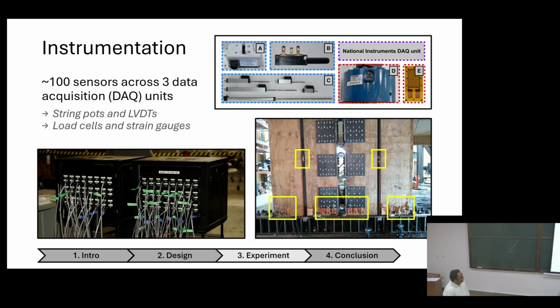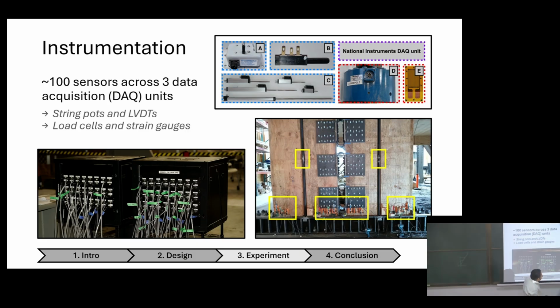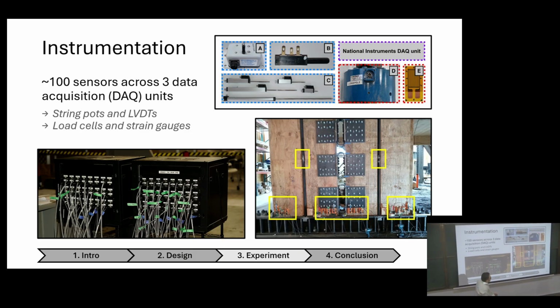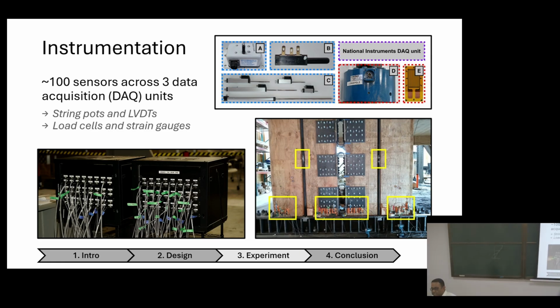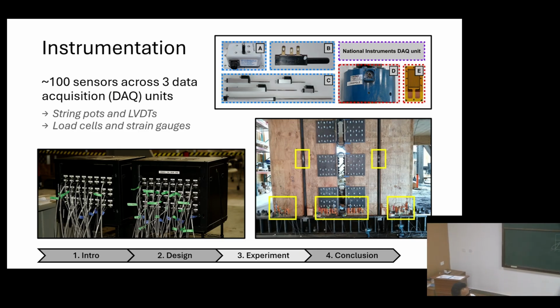All incorporated in there. So this was our only chance to measure pretty much everything. You'll see roughly 11 or 13 LVDTs across the bottom of the wall. We wanted to capture the uplift. We wanted to get an idea of plastic hinge length, which we couldn't, but we wanted to see where it fails, what's the uplift, and what is the behavior.